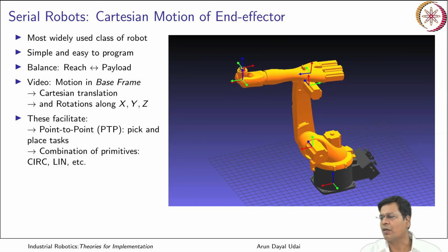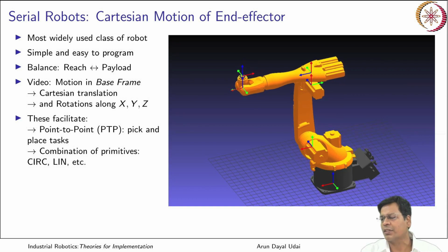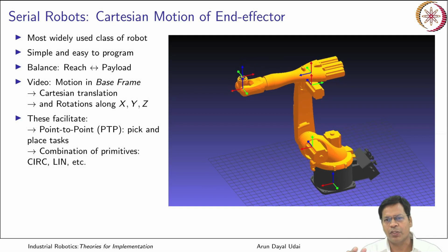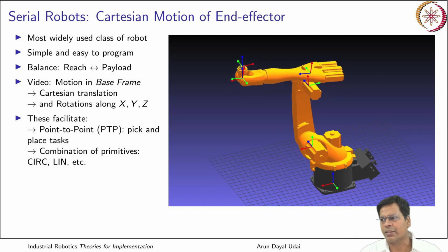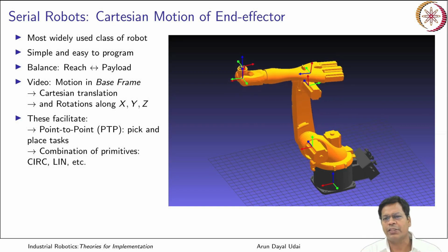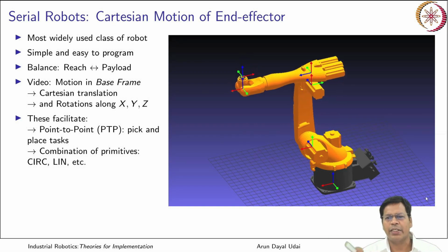Okay, it can be a combination of primitive tasks. Industrial robot controllers are pre-built with some kinds of motion, like a circular arc. They can be defined in different ways: like 2 points and a center point, or radius and 2 points in space, or maybe just 3 points in space.